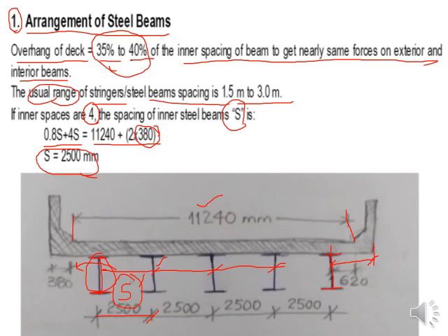So on both of the sides you are going to multiply it with 2. So 380 just coming from the edge of the curb down. You can see this figure over here, from the curb edge on the exterior side till the exterior edge of the deck slab. So this distance is equal to 380 millimeters.